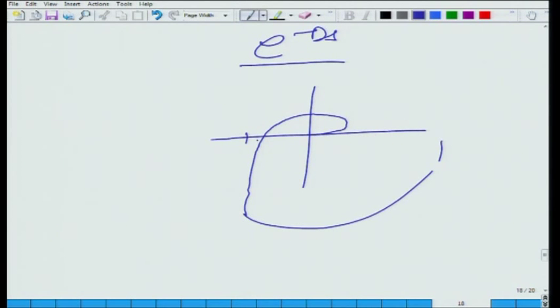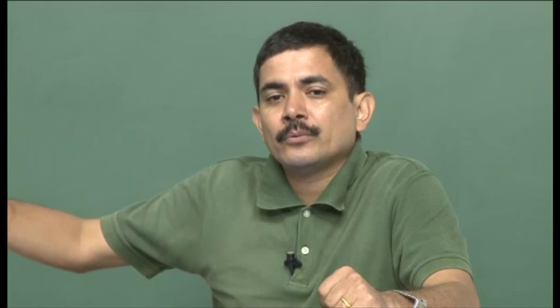So, I do not know, something like this. If you look at the unit circle, this is the unit circle, this is -1, 0, real axis, imaginary axis. You can see that I have sufficient phase margin, but then my curve is passing very close to minus 1, 0. My Nyquist plot is passing very close to minus 1, 0. So, even though I am not unstable, because my curve is passing very close to minus 1, 0, I will get not sustained oscillations, but oscillations that take a very long time to die out, even though I have sufficient phase margin.